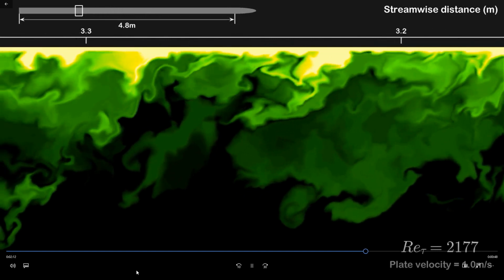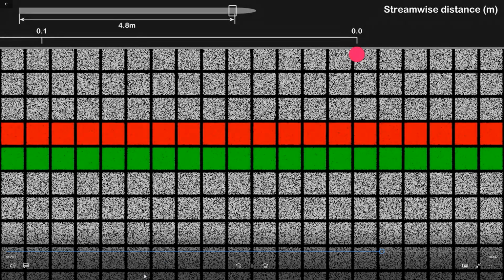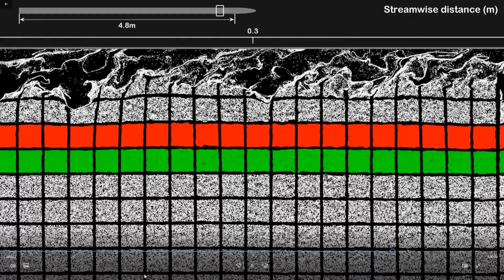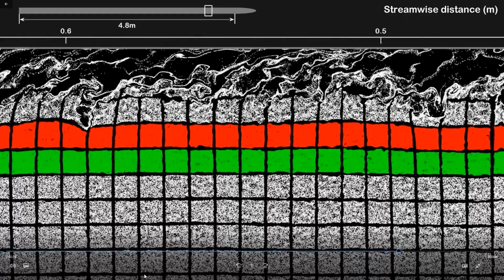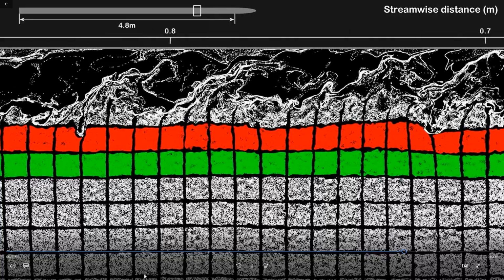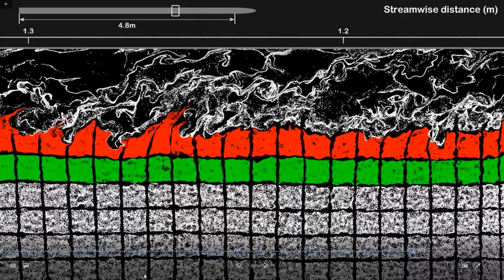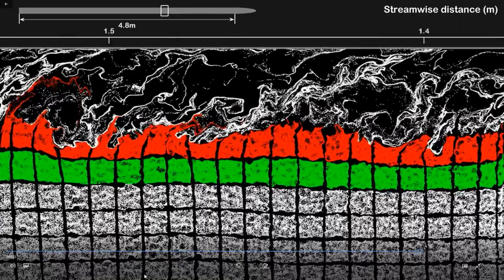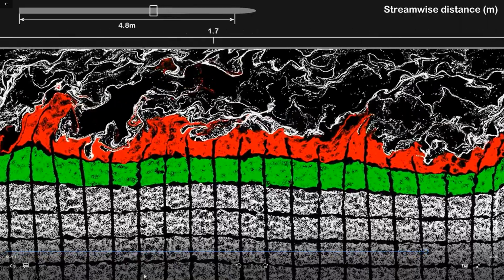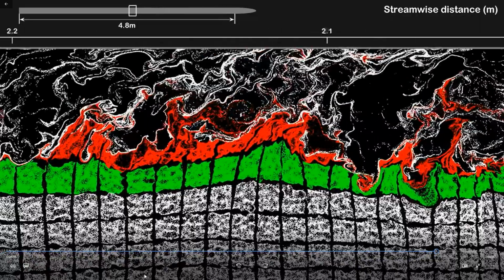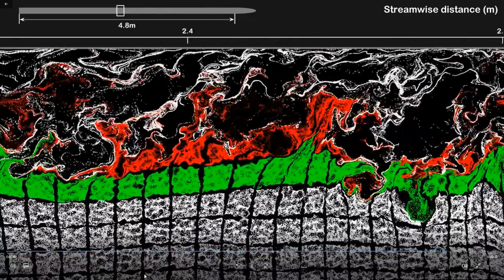And then here's another one where they instead seed the flow with a grid of particles and then model what it would do to that distribution of particles. Once again, you see that some particles are being sucked in by those fluctuations, and some are being ejected or thrown out by those fluctuations. But the key is that it's doing a really good job of mixing across the boundary layer, the portions of the flow.